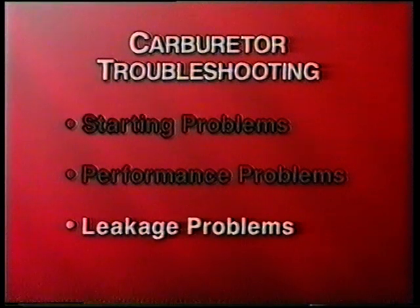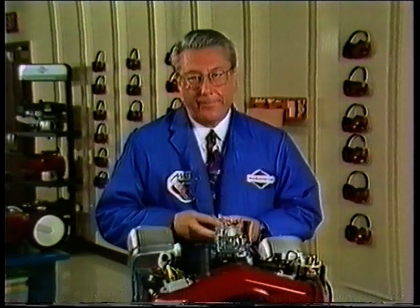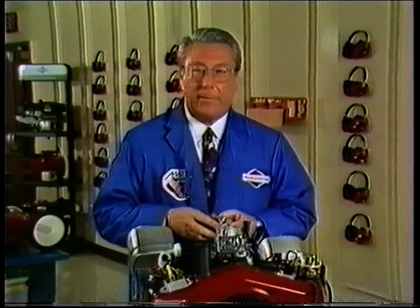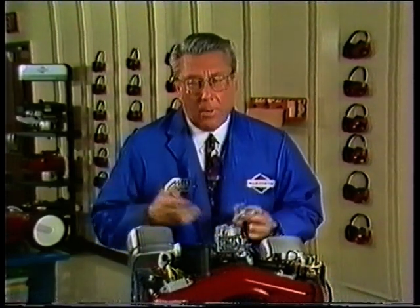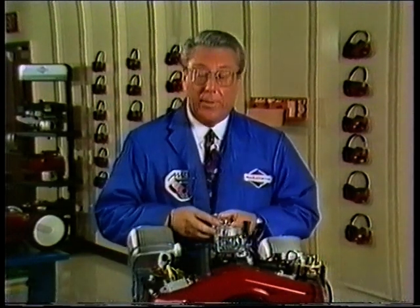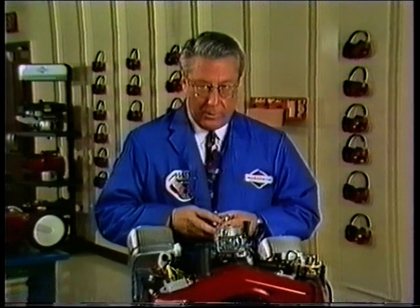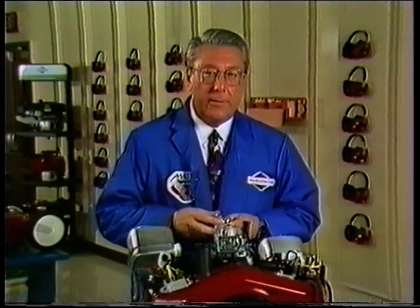Now, let's move on to our final problem category, carburetor leakage. It's one of the most annoying problems in the field. True factory defects are uncommon, and tests show that many of the carburetors returned to Briggs & Stratton over the years are structurally acceptable. So why do leakage problems persist? In a word, dirt. The overwhelming majority of carburetor leakage problems is caused by dirt or other foreign material.